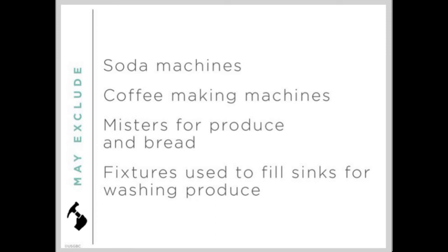Process water sinks are excluded from the fixture water use reduction calculations, such as janitor sinks, laboratory sinks regulated for medical or industrial purposes, commercial kitchen or food service sinks and prep sinks, janitor closet sinks, medication room sinks, and utility room sinks.